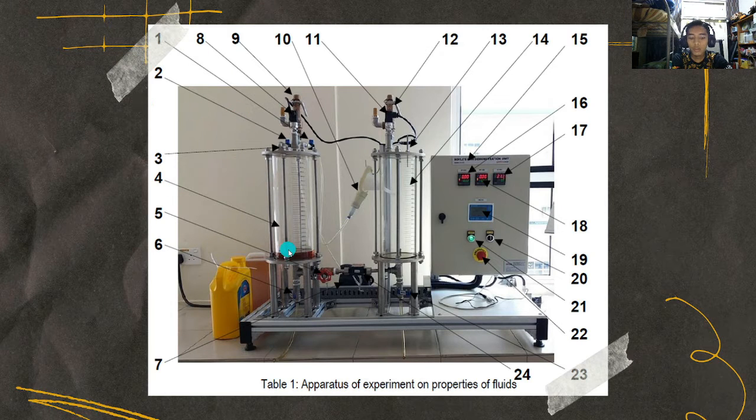So like before, we will perform the startup procedure. After that, we will open the valve BV102, the number 1, and then we will record the initial pressure reading on PT101, the volume, and the temperature of air with the TT101. After that, we will fully open the GV101, the red one, and then we will operate the vacuum hand pump, this red one with the number 10.